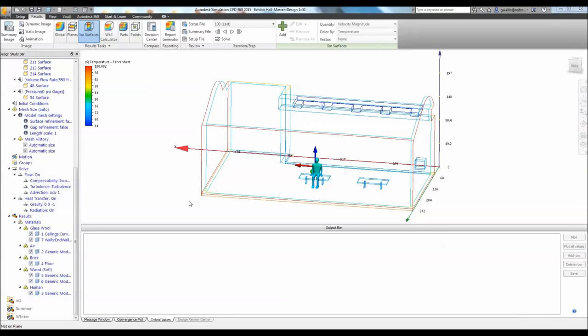The CFD simulation product calculates the PMV using several factors. Some of those factors are the local airflow velocity, temperature, clothing, metabolic rate, humidity, radiant heat exchange and things like that. This assists us in determining how warm or cold a person feels inside this space. I just want to make sure that little fella is displayed, and you can see him clearly in the room.